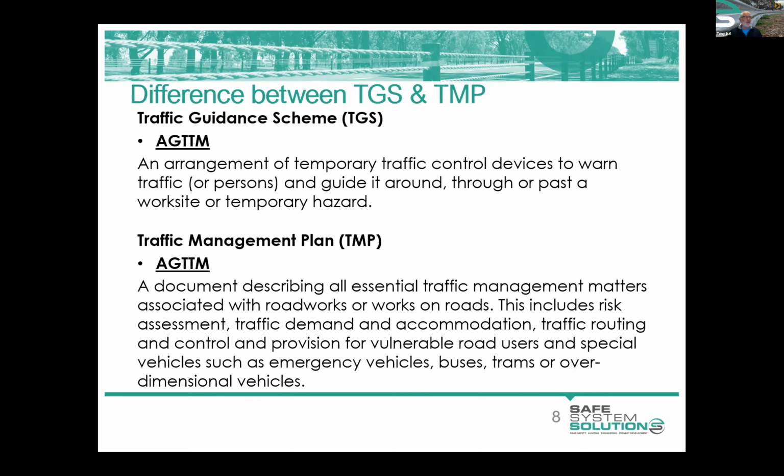And out of that plan, you will then develop, it might be 1, 2, 10 different traffic guidance schemes. It could be the different staging. It could be that for nighttime or daytime or working hours or out of working hours. All of those items that you have identified in your plan are to be managed, and that's the signs and devices you will place on the road.